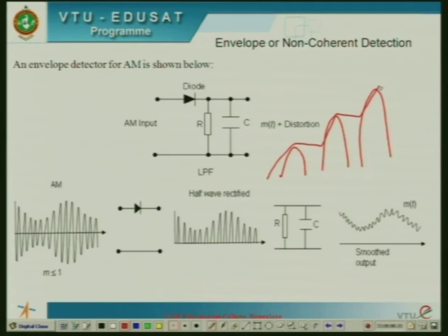It is charged. It has now reached the envelope. So now if you try to see, it is approximately like an envelope. Suppose the fourth pulse is basically like this. If the fourth pulse is like this, what should the capacitor now do? It has to slowly discharge.